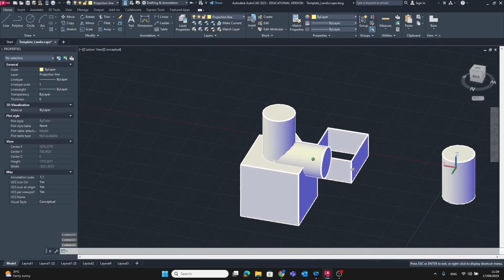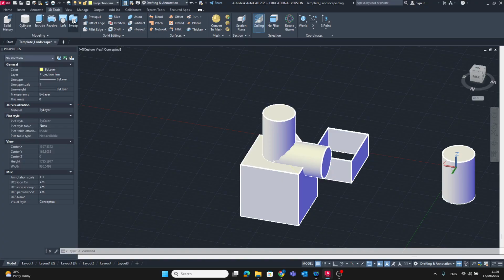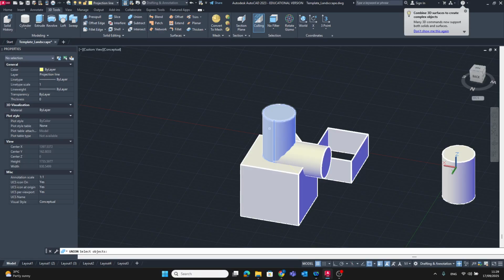For the first command that I will show you, I will combine two objects to make an L shape by using the command union. Once you click union, you click one object, and then the command will show one file, and then you have to press shift and click another object, so it's going to be 2 in total.